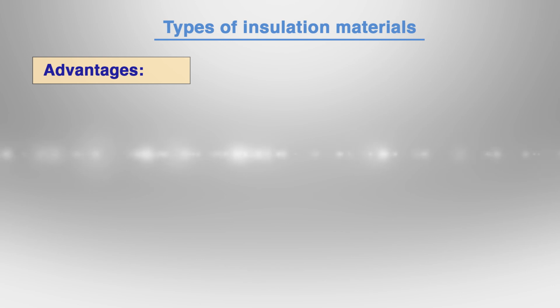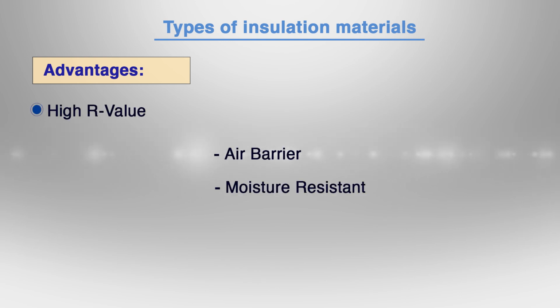Foam insulation has some advantages like high R values, provides superior thermal resistance per inch. Air barrier, expands to fill gaps and cracks, preventing air leakage. Moisture resistance, effective at preventing moisture infiltration.